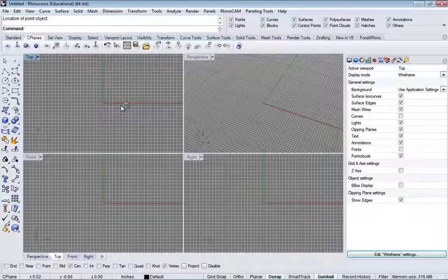And so what you can do, sometimes you can imagine that, let's say I have this surface here, and it's at this angle, and I want to punch a hole in this, for instance, or I want to add a piece of geometry onto this piece of thing. So one way to do it is to create the geometry and then move it and snap it and try to make it fit onto there. But we can tell it, use this surface and make it a construction plane, and then all my geometry that I start to create starts to happen on that surface. So I don't have to worry about angles or any of that. It's just nice and clean.